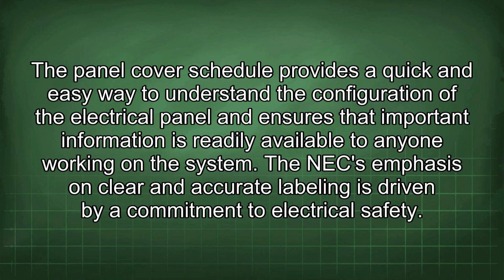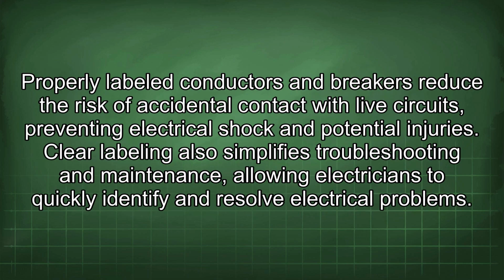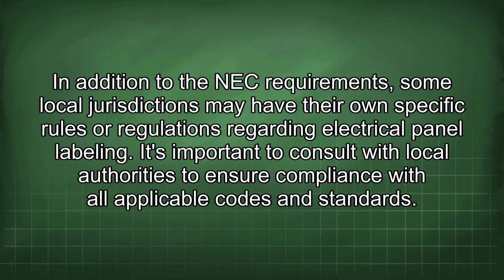The NEC emphasis on clear and accurate labeling is driven by a commitment to electrical safety. Properly labeled conductors and breakers reduce the risk of accidental contact with live circuits, preventing electrical shock and potential injuries. Clear labeling also simplifies troubleshooting and maintenance, allowing electricians to quickly identify and resolve electrical problems. In addition to the NEC requirements, some local jurisdictions may have their own specific rules or regulations regarding electrical panel labeling. It's important to consult with local authorities to ensure compliance with all applicable codes and standards.